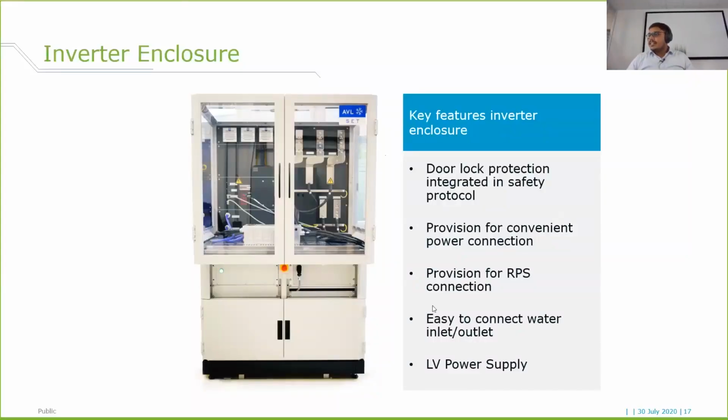And secondly, there are easy connection terminals, which are plug and play. It is just that easy to connect the inverter to the DC side, and also the signal interfaces and cooling units and so on. It also additionally comes with a discharge unit, which helps to rapidly discharge the connected inverter after a high voltage test, so that it can be easily demounted to carry out further needed activities in the testbed itself. And it also comes with a low voltage DC power supply to provide this particular inverter with the control power supply, so that the controller can operate.